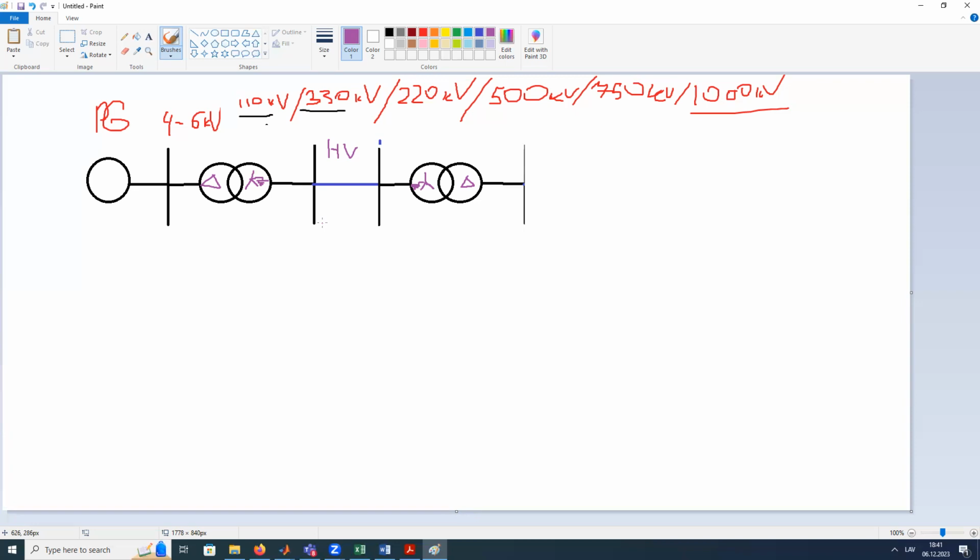And the easiest type of fault to be detected is a grounded fault when we use a star with ground connection for the transformer windings. The easiest way, because for this connection we have a very high fault current, and if we have a high fault current, it is quite easy to detect.